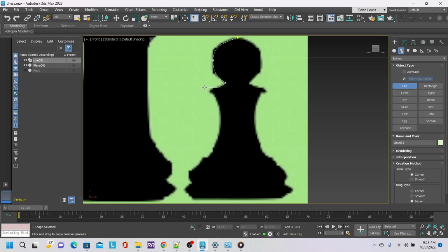Now, the magnitude is going to be too great going in this direction for following the silhouette. So what I'm going to do now is hold down the Alt button and move my cursor closer to that point. I'm just going to go ahead and bring it down a little bit, and that's going to set the magnitude and direction of the next curve in the direction of the cursor. So when I release, you can see the lines going in that direction to begin with. So I'm going to go to there, and then I'm going to click.